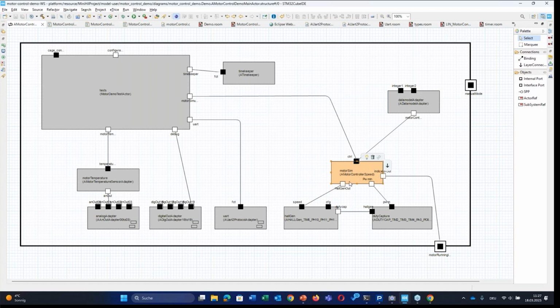And then the motor calculates, for example, with 20-30 kilohertz. It calculates the new speed based on the PWM measurements and informs the hall generator about the speed it needs to simulate. And the hall generator has 3 digital outputs.